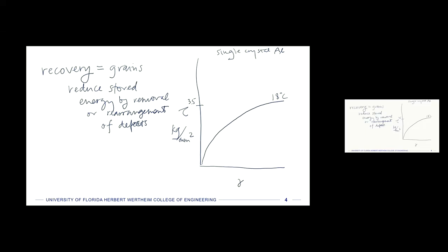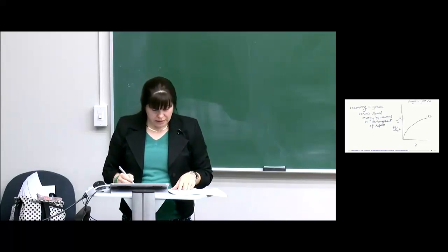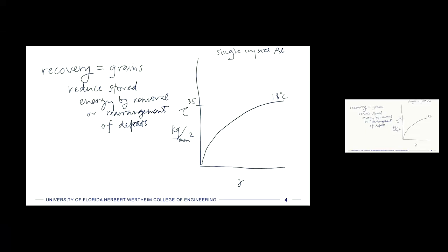So as we start to raise the temperature, so now we have this material at a steady state temperature, and we start trying to make it slip. We don't get quite the amount of strain hardening that we got before. So this would be like 100C here. So it's about half the amount. Sorry, let me say that's about 200C. It's about half the amount. And then once we go up to temperatures close to the softening temperature, like 500, 600C, we're way down here, we get almost no strain hardening, right?